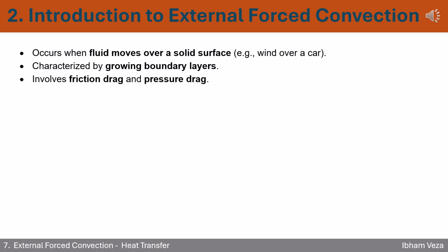One of the most important things to understand here is the concept of a boundary layer. As the fluid touches the surface, it slows down and forms a thin layer called the boundary layer, which keeps growing the farther it flows. This layer controls both the heat transfer and the friction on the surface.